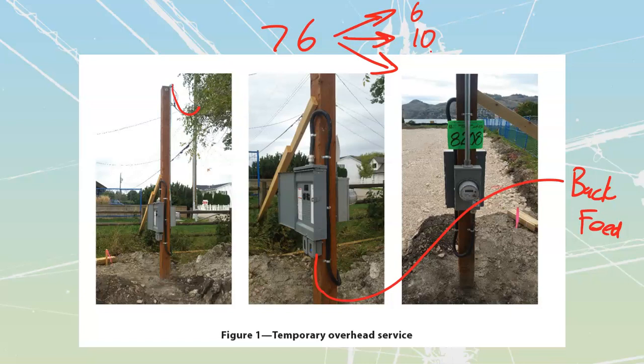Off of there, motor loads, if you're going to have permanently connected motor loads in some large scale construction, particularly in low-lying areas, you're going to have permanent pumps that are going to be set up where they're digging down for foundations and footings and stuff like that as well. So proper sections of the code, you've got to still follow them where applicable, and then 76 just tells us about the actual service itself, and everything else that we wire out of it will follow the applicable sections of code.